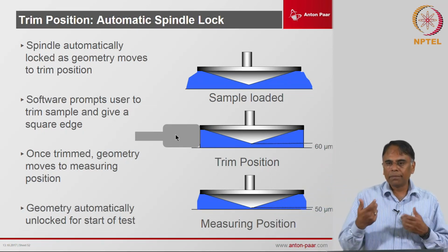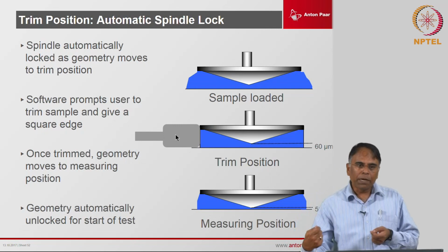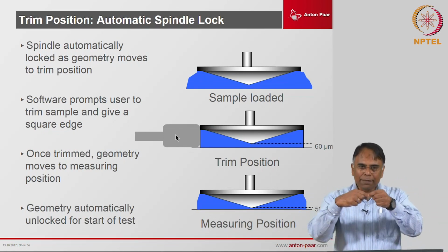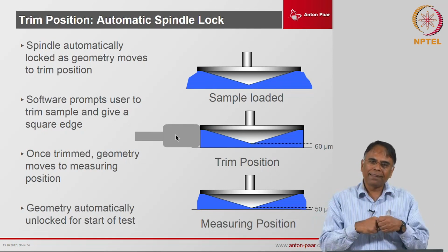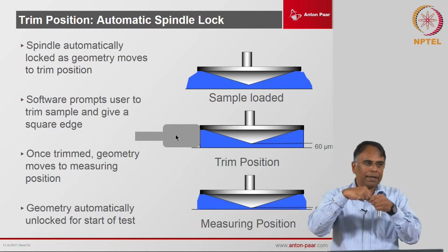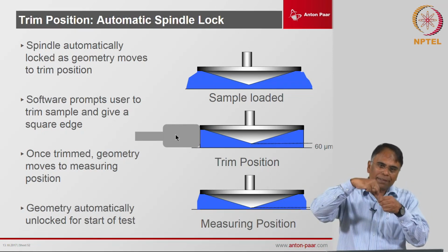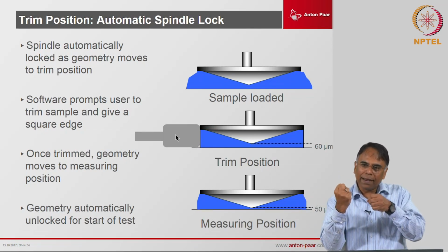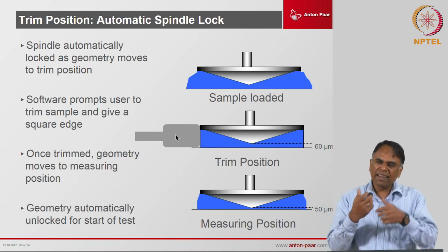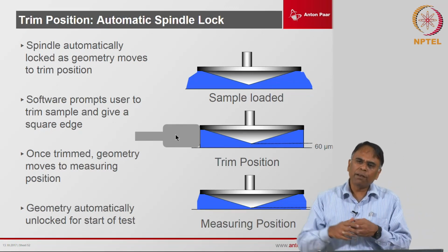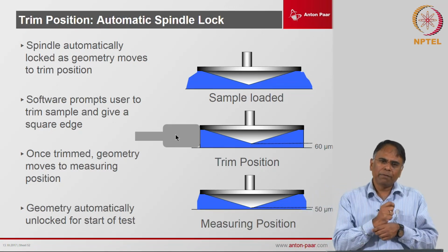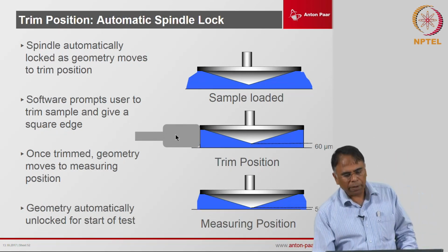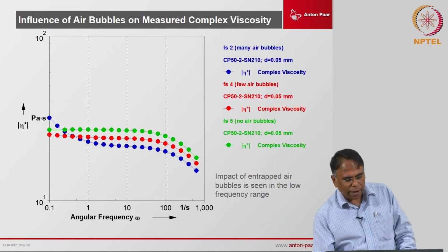If you take a very cold trimming tool and directly trim a hot sample, just imagine what is happening at the trimming edge. You have a sudden quenching of the sample, and it will also be difficult to trim with a cold trimming tool as compared with a warm one. A warm trimming tool is easier to handle.